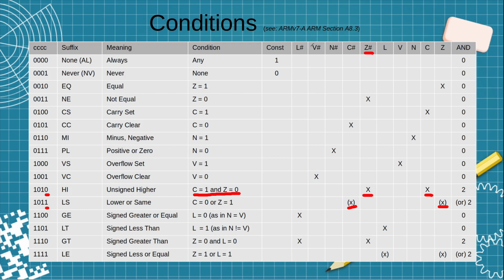The next one's a little interesting as well because I actually need the inverted L flag for that to work. And again, my L flag is where L is not equal to V, and that's run through an XOR gate ahead of its presentation off to the control module. But then its inversion is simply the L flag. So that still holds, but I need to extend the inverted L flag off to my control module.